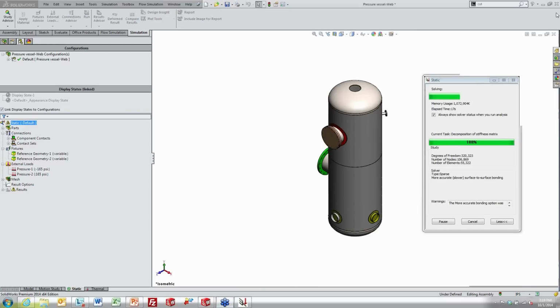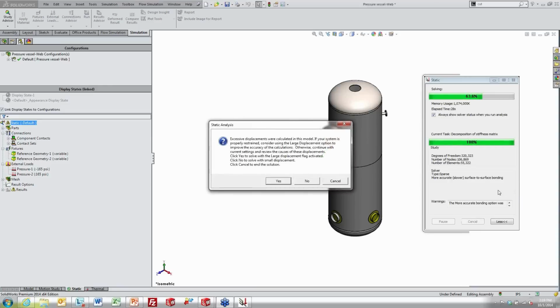While it runs, let me just see if there are some questions going up here. I see someone has said, can you break the meshing tasks for an assembly into both types, standard and curve? The answer to that, unfortunately, is no. You have to do it all one or all the other. So the best way to get around that is to stick with one, like standard, and then use mesh controls as your second option.